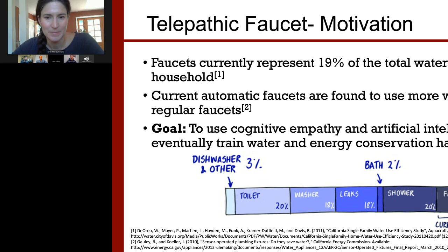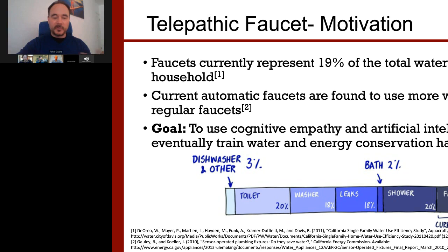Yeah, I'm trying to dig through my notes from last week to figure out which specific presentation I'm trying to reference. But there was one presentation that was really talking about Legionella growth in distribution systems. Unfortunately, I can't find my notes quite yet. But the general takeaway was that Legionella grows really well between 80 degrees Fahrenheit and 110 degrees Fahrenheit. So that's very much backing up your comment, Alex. Warm water does not benefit microbe removal. I'd say it's worse than that. Warm water encourages microbe growth.